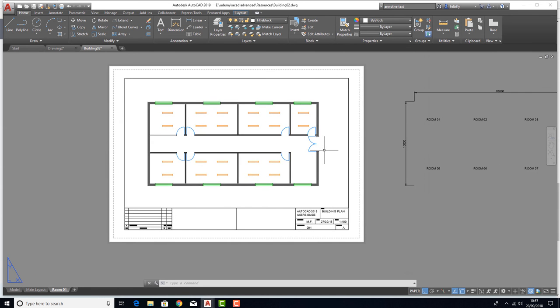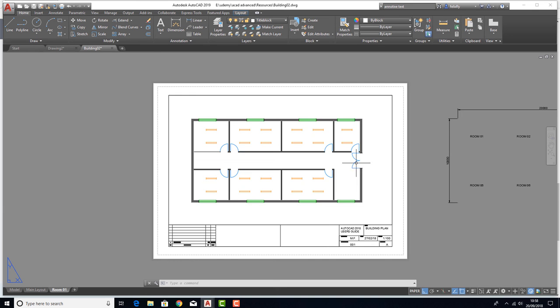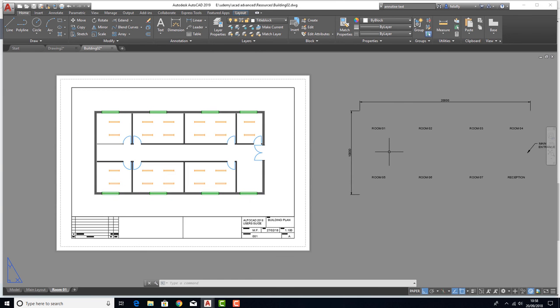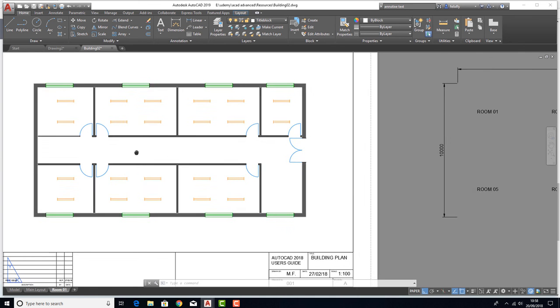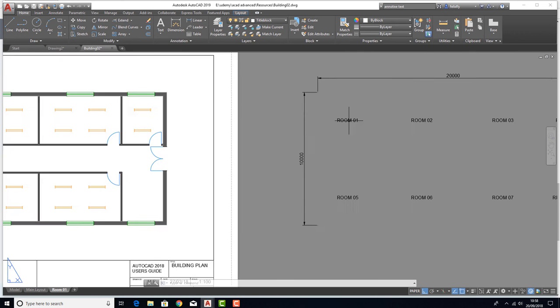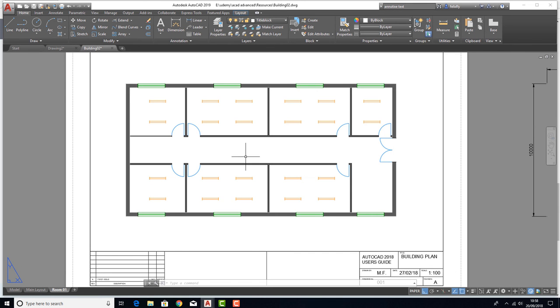It just looks amateurish basically. It doesn't look professional. You want the same kind of follow through with the same sizes and styles. Usually in Britain we would use something like 3.5 height for a title and 2.5 for dimension. So you can have different sizes for different types of text like titles and things, but you want the same font and you want to follow through with, if all the titles are the same size, all the dimensions the same size, and all the text the same size. Okay, it just looks more professional.